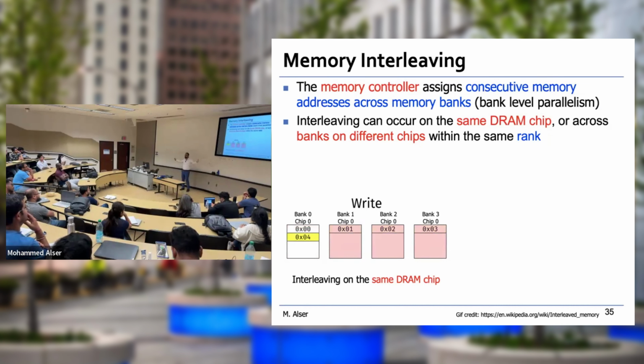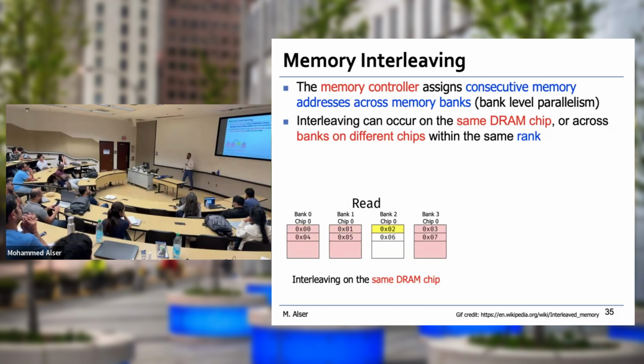So whatever the size of the matrix that you try to fit in the banks, you just bring whatever you could fit in the first row, you move to the second bank, third bank, fourth, and then iterate. So if you have 1 million, you could divide it, for example, 200 bytes in the first row. You could fit that amount in here, then there, and you continue doing that. That's what we call 4-way interleaving.